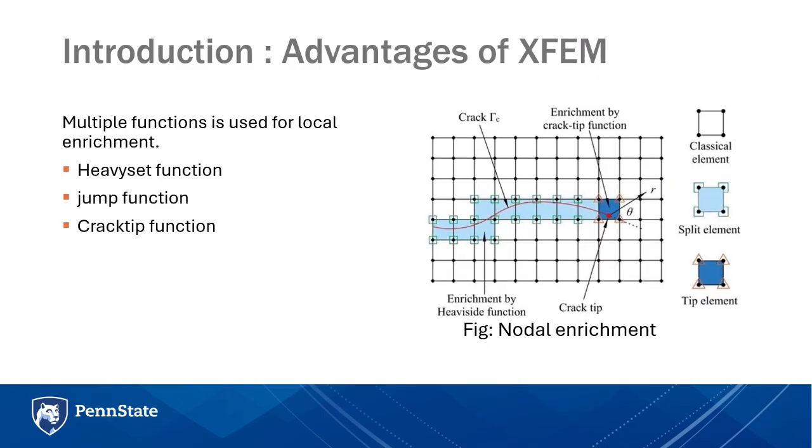There are multiple functions for local enrichment, for example, Heaviside function, jump function, crack tip function, etc. In the figure, you can see at the crack tip, the crack tip function is used for local enrichment.